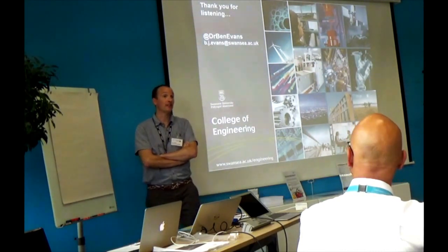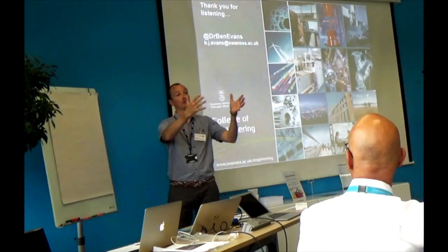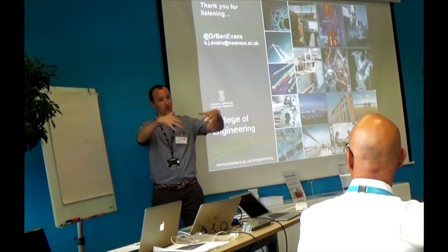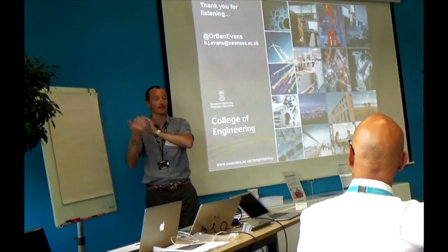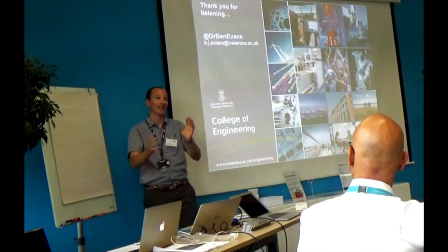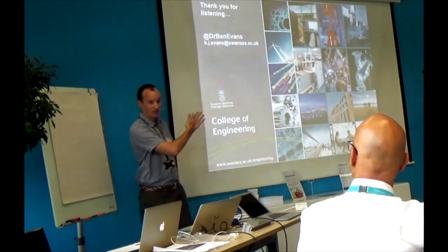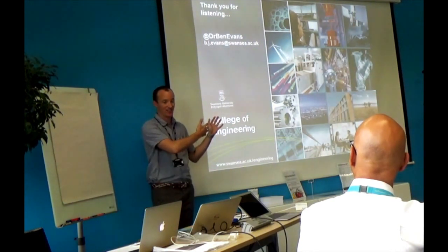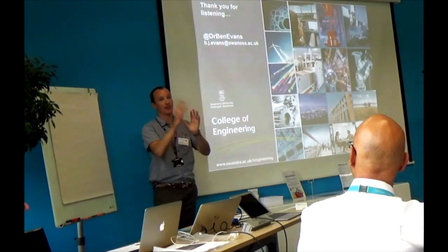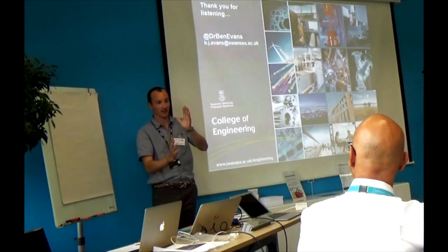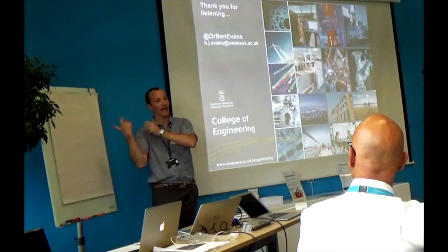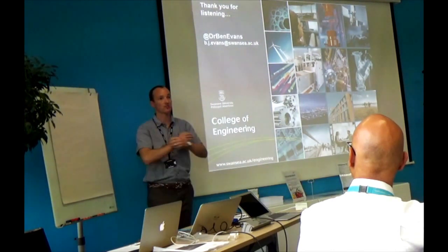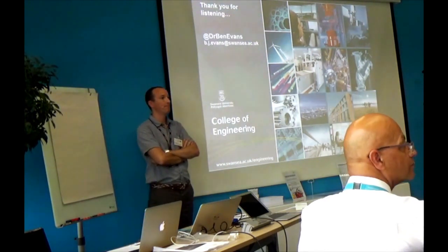So effectively we're doing that by blowing out all of the air that goes into the engine bay out the base of the car to try and reduce the base drag as much as we possibly can. And again, how well we're approximating that in the CFD model is a big question, because it's difficult to model that. So we make some assumptions about to what extent the predictions on the base of the car in the model can be alleviated by blowing air through the base of the car, and there's uncertainty.